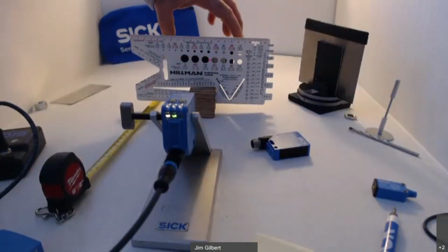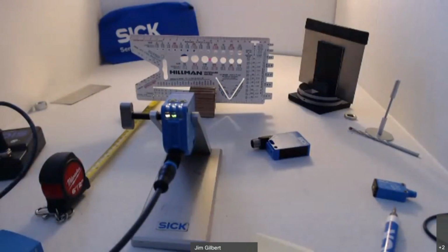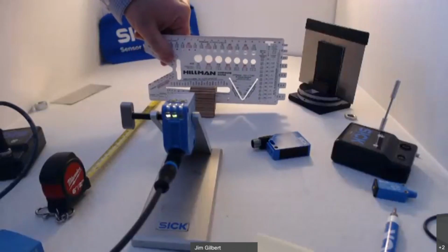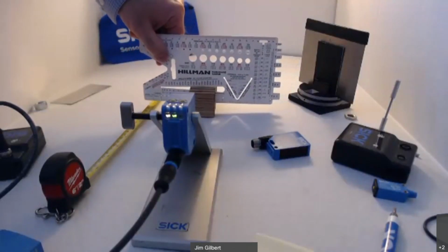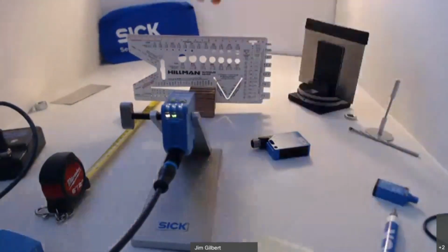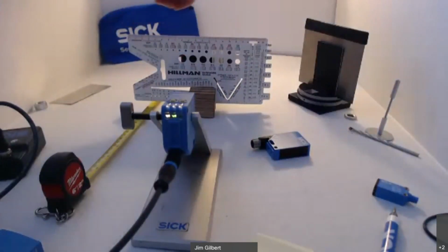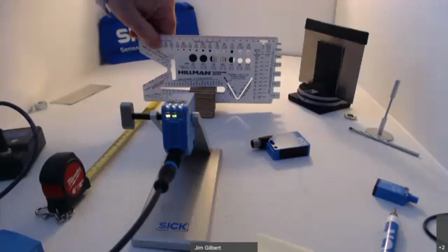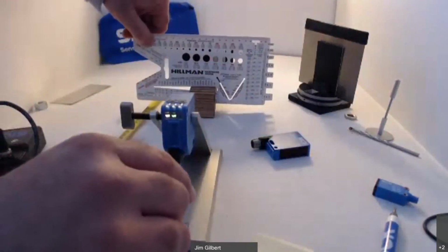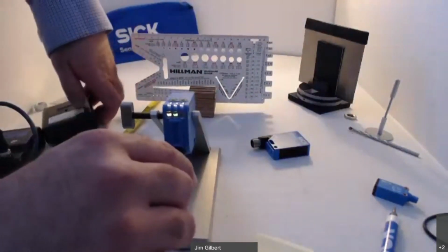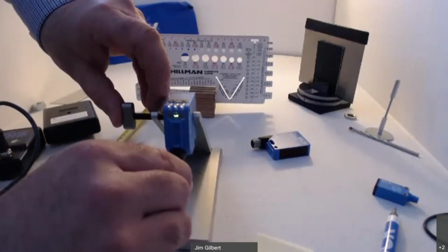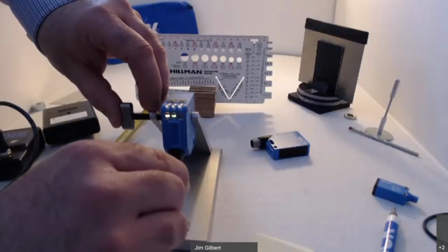Again, I'm at about the diameter of these circles. I'm going to pull away this black box. This is just a reference so I can know where to teach the sensor. As I slide it through, you see that I'm having a little bit of a problem detecting now. But if I bring in this background again, it can change its behavior. So the point is that depending on how far away the background is, that can change the behavior of the sensor. For your application, it can be really important whether you have a background or not.